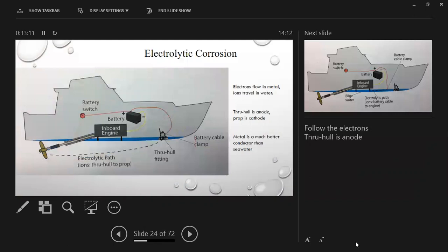When that occurs in the bilge, that would cause the ring of discoloration around the through hull too, right? If you're overprotecting any metal, you'll get a discoloration around it from the hydrogen, from the hydroxides. I had a situation where I was doing a boat and there was a halo around all the metal objects, through hulls, trim tabs, everything.